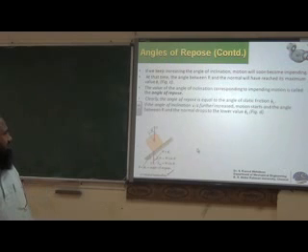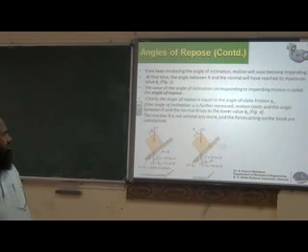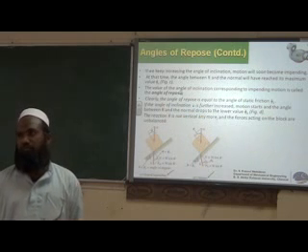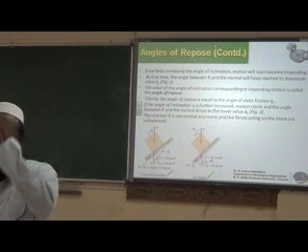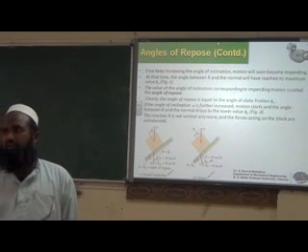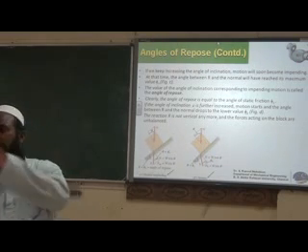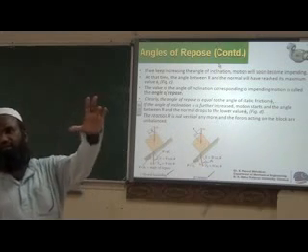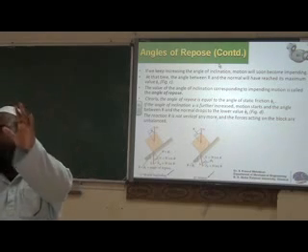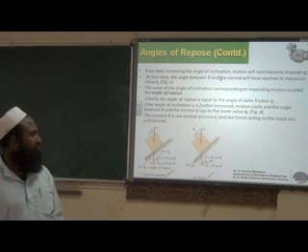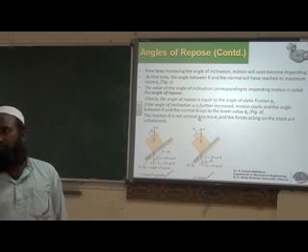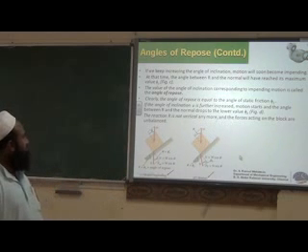If you increase the angle further, you get a situation like this, where theta equals phi. So this theta is called the angle of repose. You have two angles, angle of friction and angle of repose. The angle of repose comes into existence when you have an inclined plane, with a body on the inclined plane. The maximum angle you can tilt can be found by considering the angle of repose or angle of friction. We'll solve a problem so that you can understand how it comes in.